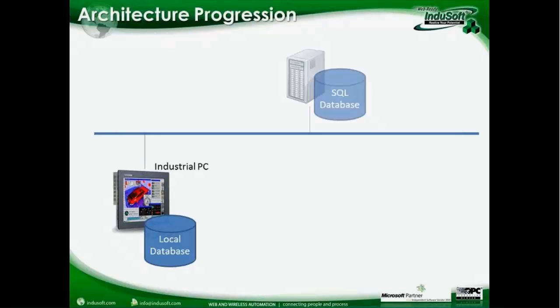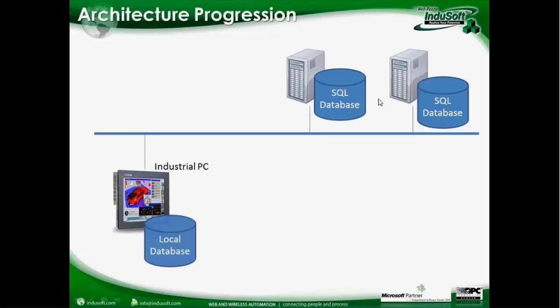file, and bring that into Excel, let's say, and do whatever you want to with it. But as your system grows, maybe you'll find that you need to log to a remote database, and maybe that becomes SQL, whether that be Microsoft SQL or MySQL, FoxPro, Sybase, Oracle. We can do that. And then maybe your system grows again and you realize that data, I need that data and it's critical to my system. So maybe you add a redundant server in here so I can log to redundant servers. InduSoft Web Studio has built in the functionality to be able to log to redundant servers. And it's very easy. You just choose it from the menu and set up where that other database is.